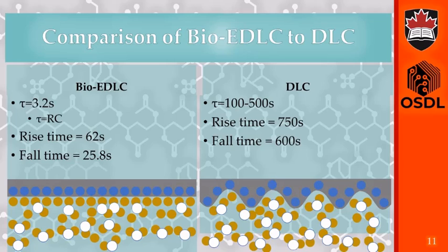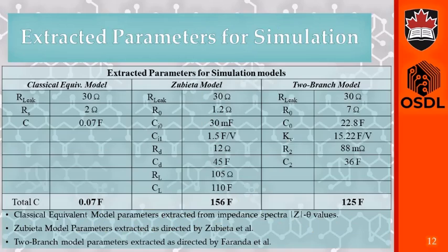We simplified the Bio-EDLC fabrication by using a smooth electrode unlike regular DLCs, which reduces surface area and therefore adsorbed molecule quantity. In addition to the gel matrix and the mildly acidic nature interrupting the hydrogen bonding, this contributes to faster charging, but negatively impacts the capacitance mechanism.